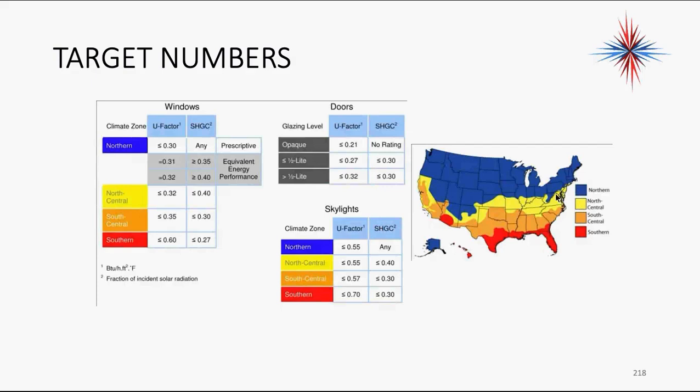You guys are almost right on the border between the north central and the northern. Depending on your building office, they may want you to work for the north central climate zone or for the northern. If I were doing an install, I'd argue that I do my air conditioning for north central and I do my heating for northern. Keeps it safe in the middle.